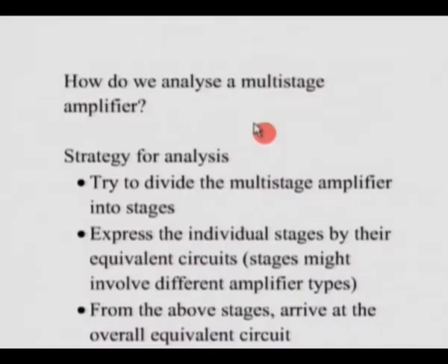So the strategy in analyzing a multistage amplifier is first to divide it into logical stages, and then to express these individual stages by equivalent circuits, and the stages might be of different amplifier types. As I said, you may not be able to have a voltage amplifier equivalent circuit, so depending on what is convenient from the analysis point of view, we could do this.